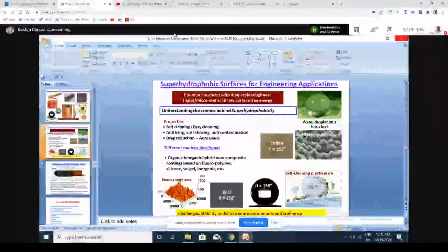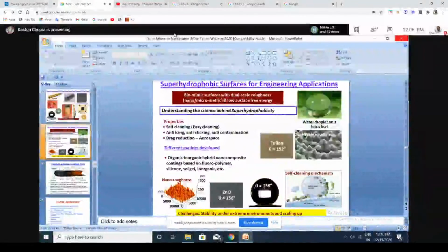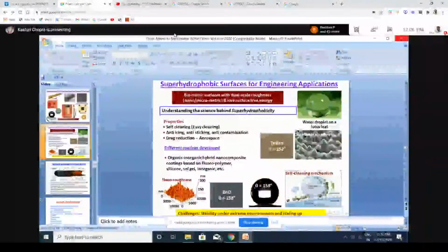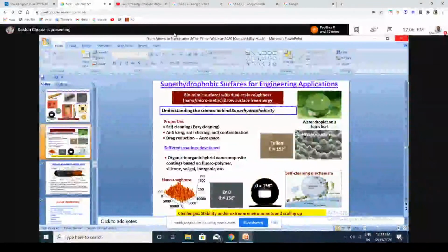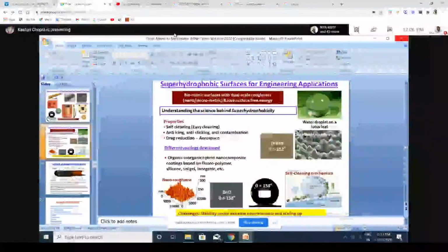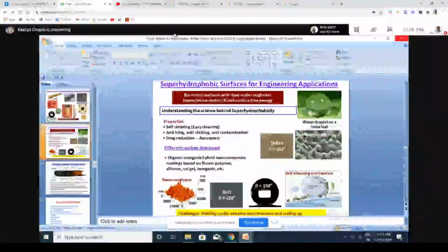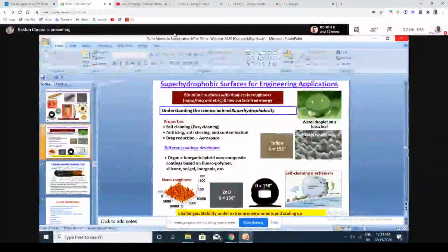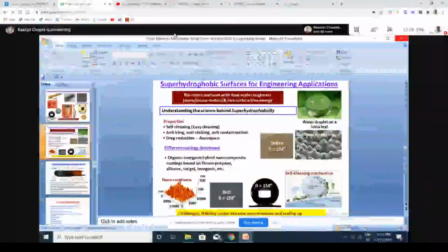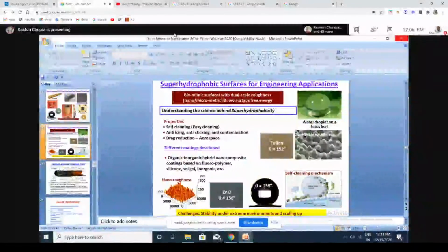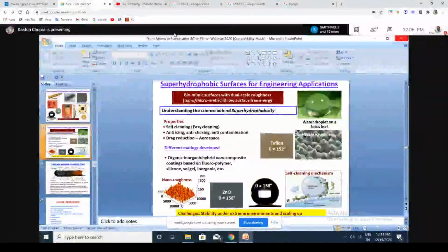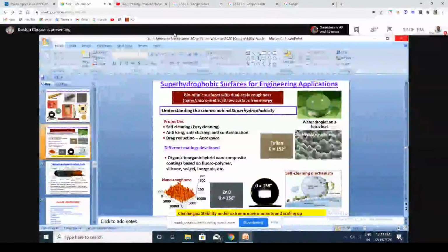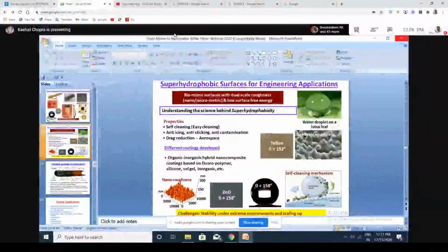Well, how do you copy that structure? This is a beautiful double roughness structure. And it turns out very nicely. You can deposit zinc oxide so that it is very rough. As I said, you can make it very smooth if you want. You can make it very rough, like pillars, for example. So it's shown here, nano roughness. You can make a nano roughness, and lo and behold, this becomes a beautiful structure for solar cells to be coated. Actually, this is not as simple as that. There are a number of things that have gone in. And now I think when you buy the new solar cell panels, hopefully they will come coated with this material,